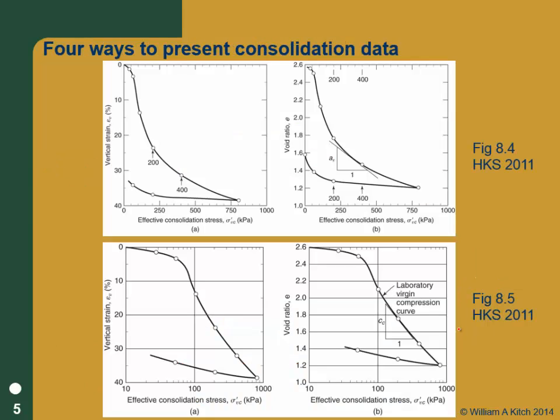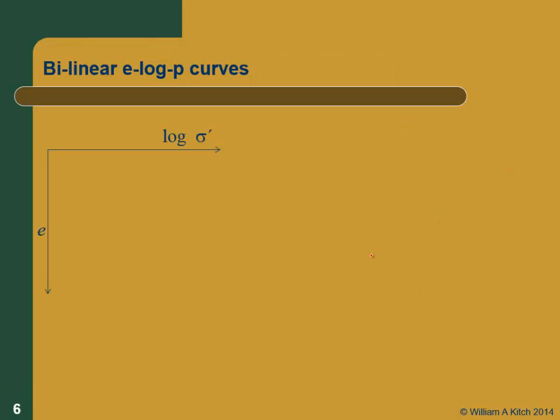So we've talked about this already, that I can plot these data either in arithmetic space or in semi-log space. And no matter how I plot these, no matter what the field conditions are, I'm always going to see some strain softening behavior early in the sample, almost always. So normally we're going to get some laboratory curve that looks like this. It's got some curvature to it.